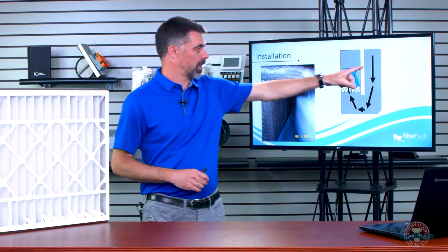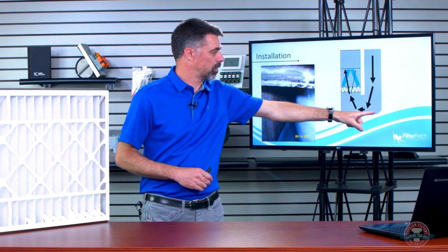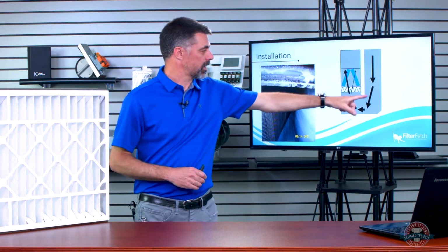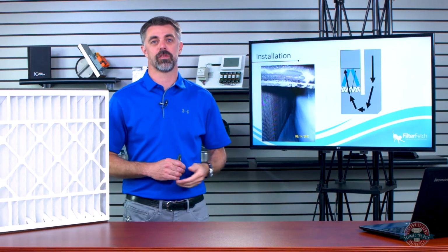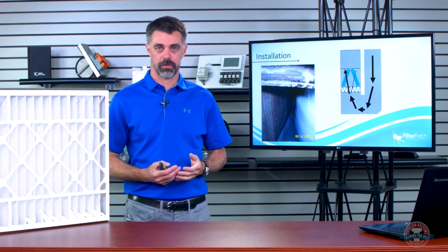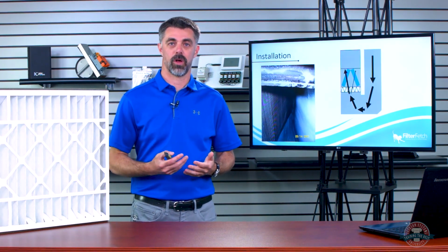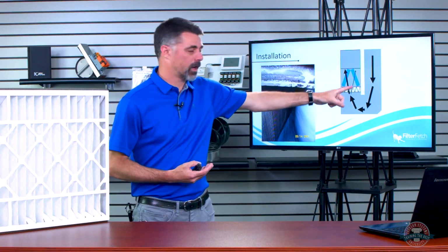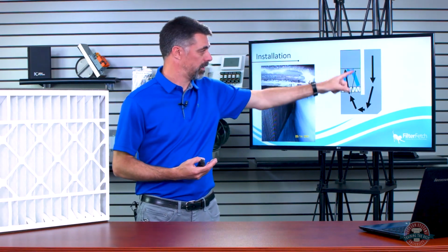This was the duct configuration on there. We've got the airflow coming down here, but there's no turning vanes in either one of these corners. So when this air came over here, even though the filter was here, most of that air split and went to the left-hand slab. It had a small refrigerant leak on it, got a little bit of loss of charge. So my saturation pressure dropped, I had low airflow through this side, plenty of airflow through this side, and it froze up. That was an interesting find.